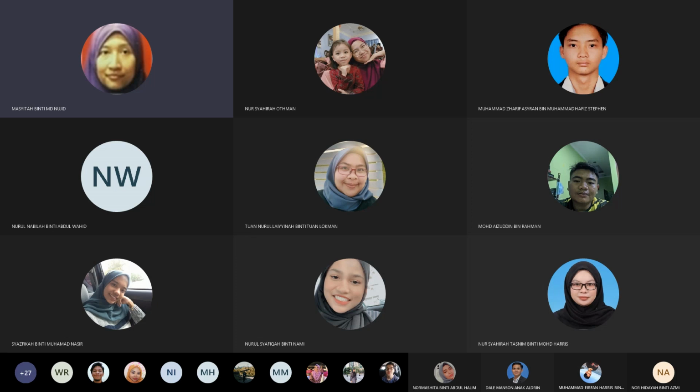And then place your ruler at this position, the beginning of the height for the right side of the slice H1, until the end of this base here at the slip circle. That is H2 for slice 1. Let's say we got 2 centimeters. So you mark here 2 centimeters. This is my assumption. Actually, you can get the right height using the ruler. So you measure from this height to the end of the slip circle, how much its height is in centimeters. So let's say 2 cm if you get it. So that's why I ask you to redo it again.